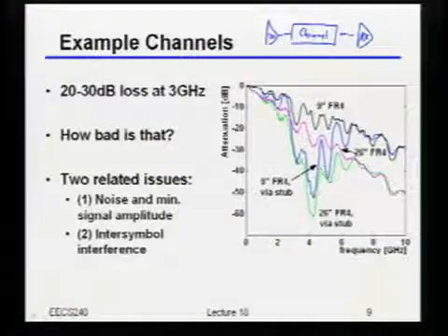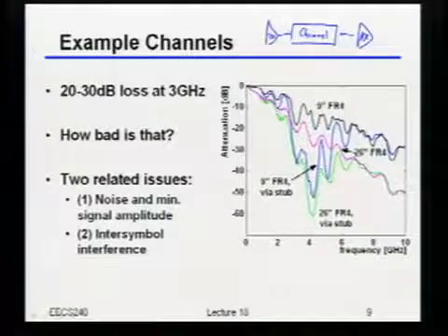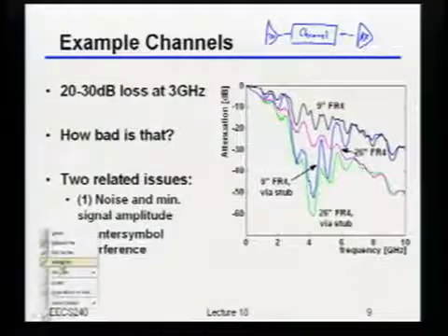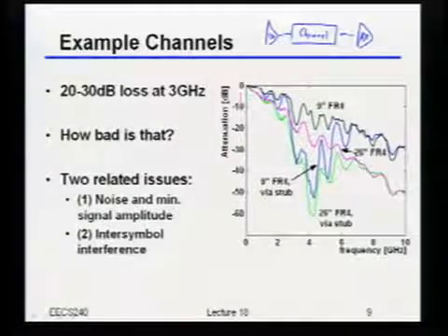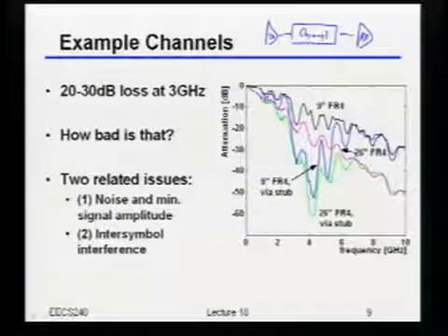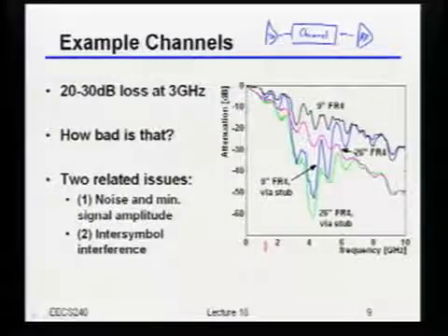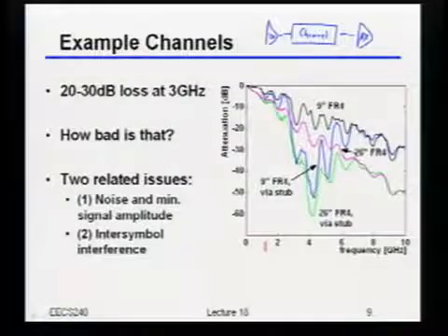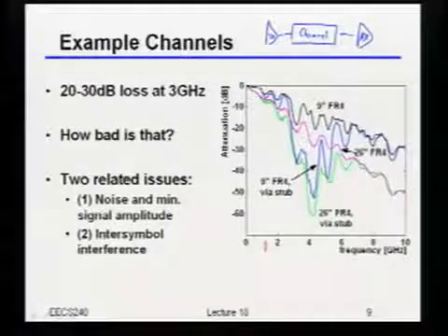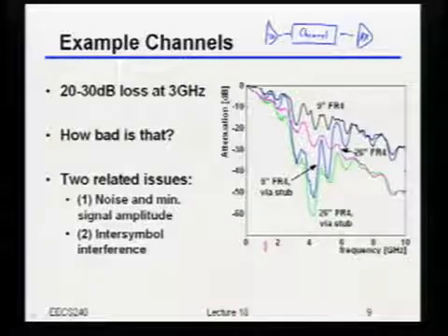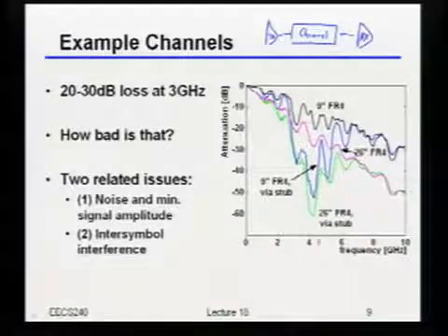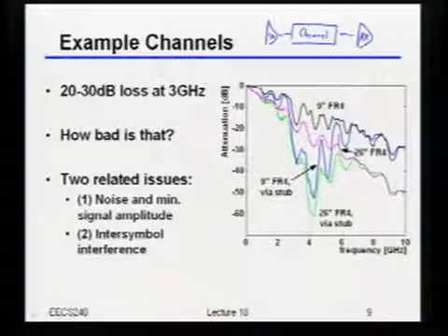So if I take all those things into account, what I'm usually interested in is basically just how much attenuation I'm getting from that channel versus different frequencies, okay? And remember, since we're trying to go at very, very high data rates, let's say 5 to 10 gigabits per second, something like that, then I'm going to care about the characteristics of that channel up to some pretty high frequencies.